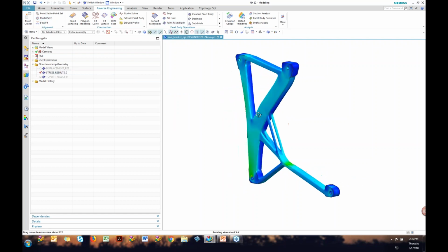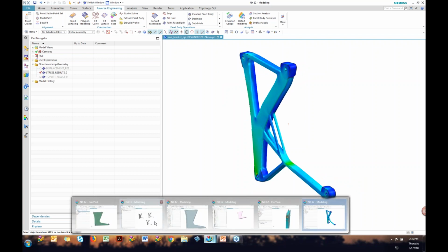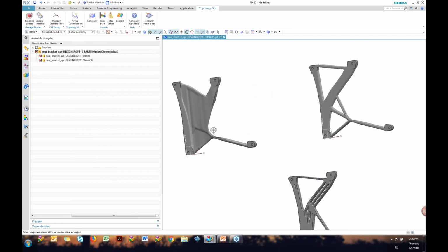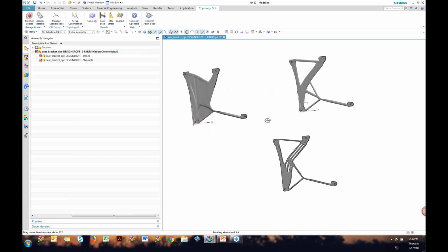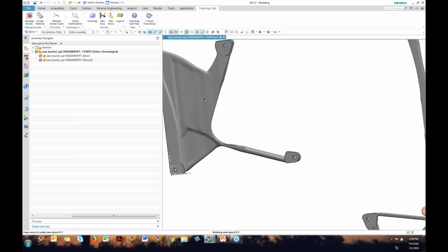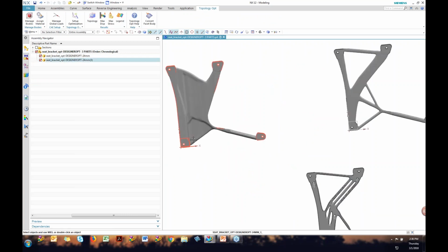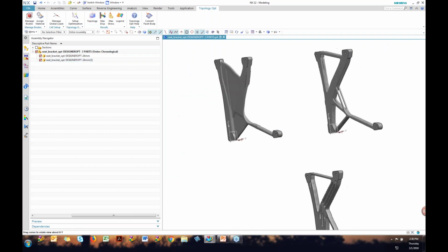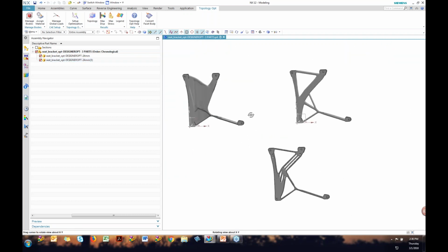Now, one important thing when you are using this is you can get all sorts of different results. I did this little example where I specified different design constraints. I said, hey, give me one with more lattice type structures. Give me one that didn't give me any holes. For this instance, maybe you didn't want things to be falling between the seats. Maybe you want no fills, and it just hollows it out, and it gives you that region. But you can tell each one of these structures is still following the same sort of load path. So they all have the same load path. So it's important to understand the load paths and use that as the design. So realize this isn't your final design, but it's a good way to start.